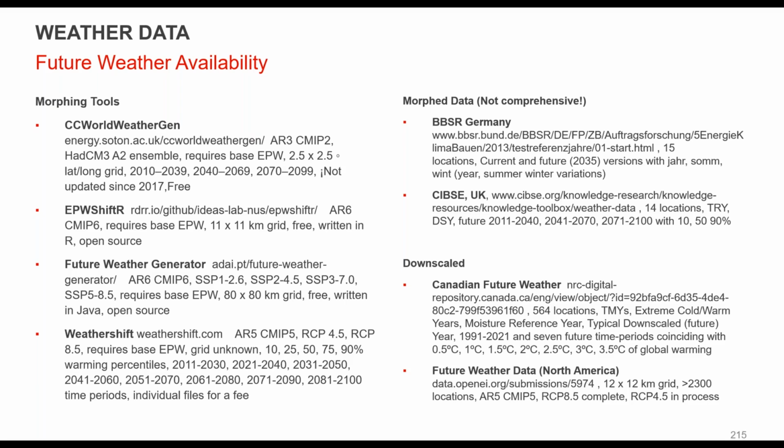George asks, which of all possible TMY should we use according to 90.1? 90.1 just says hourly data. It doesn't specify which, but I recommend using the more recent data, partly because what we're seeing is a real shift. On the chart I showed you for Washington D.C., there's a big shift, a drop of 10 to 15% in heating energy for a lot of locations, and cooling is coming up some, but we're seeing a big shift downward, and that may affect your designs.